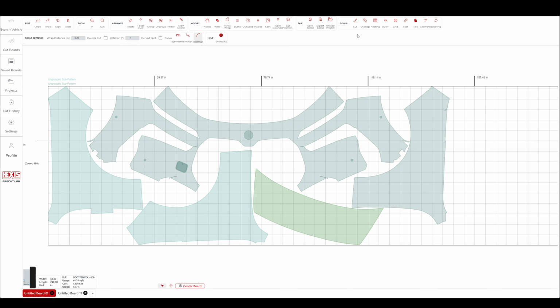Excellent. So now you'd be ready to use the cut tool and send your templates out to the plotter for the final cut. And whenever you select the cut tool here, it will automatically trigger an overlap detection check just as a final last step warning to be absolutely certain everything you're going to be sending will work perfectly.